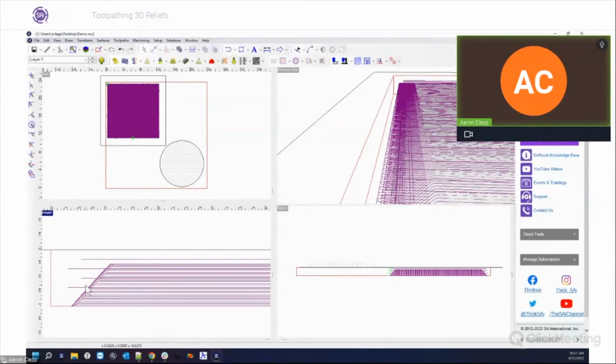So this is going to be a good way for you to combine two tools to make the cut go faster. You could just cut it with one tool, and that works too. But if you're wanting that fine detail, this is where using a step rough, hogging out all the material around it that's not necessary, and then coming back with your smaller end mill at a faster feed rate in one pass will help you do that. So that's going to be another tip or trick to use in this case.